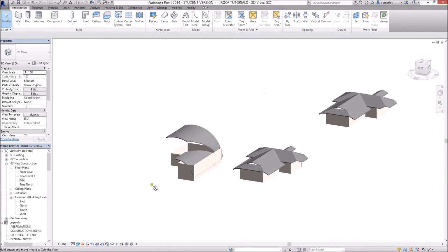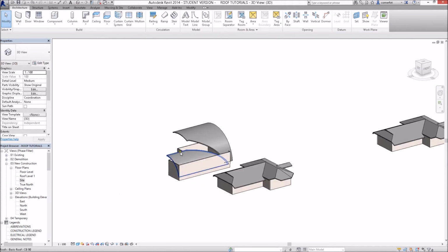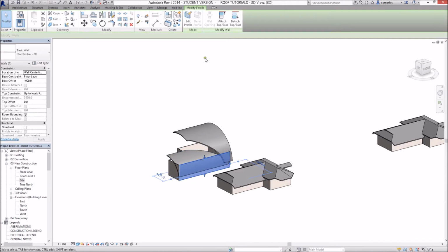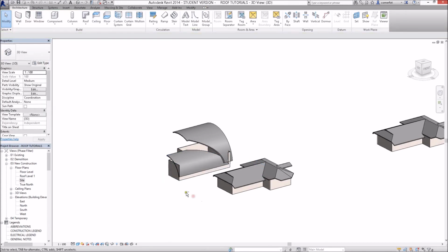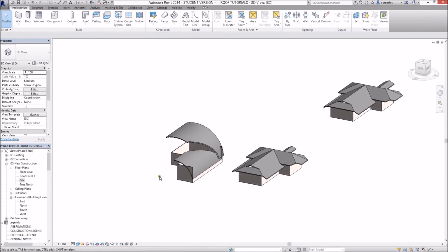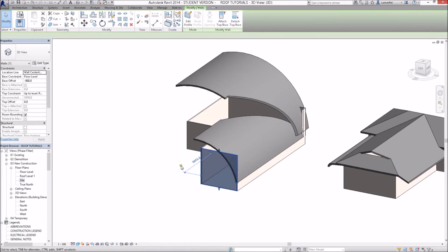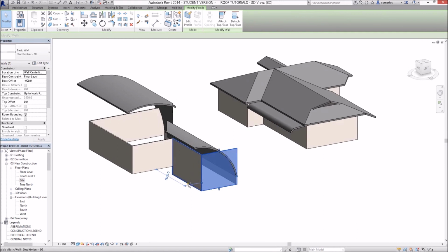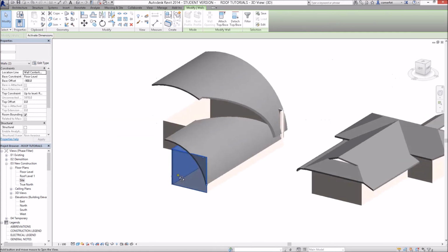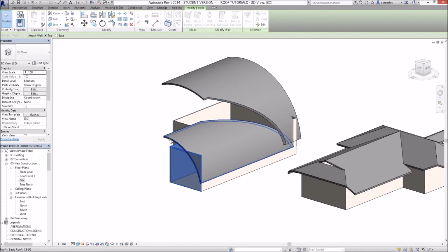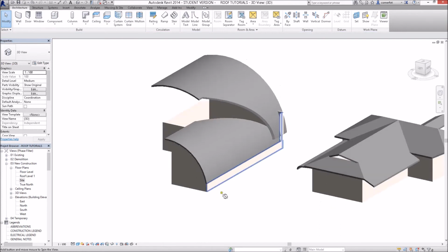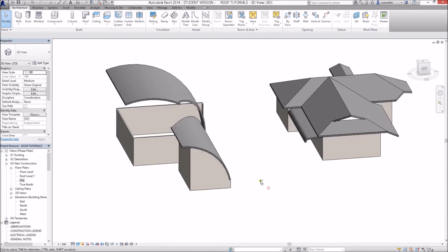Okay, so to finish that building now, this wall, my intention is to attach the top of that wall to that roof. So it would do something like that. And so once again I'll attach that one, and I'll control select that one. And probably, I'll do it that way anyway. Attach the top, yes it is attaching the top to there, so that's that part of the building closed off.